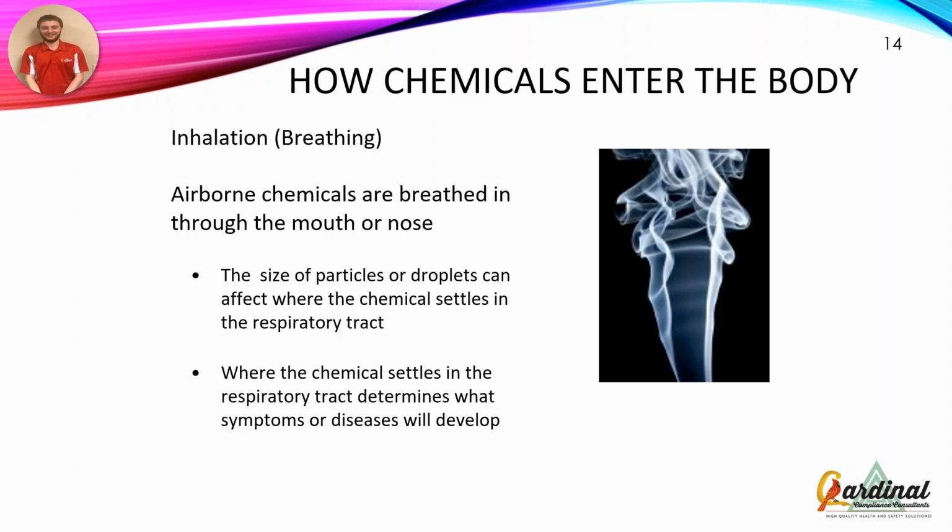Okay, so inhalation and breathing, definitely one of the most common ones as well. Simply not wearing proper respiratory protection is one reason why you might inhale something. Or just walking around doing your normal task, whatever it might be. Vapors come up. Gasoline even has vapors. They're pretty simple chemicals we use every day that unfortunately people inhale from their nose or their mouth. And unfortunately with that, sometimes people don't even recognize that they're there until it might be too late. So definitely try to be on edge for that. Make sure you're aware of what chemicals you are working with, your plant works with, and who people around you are working with at the same time.